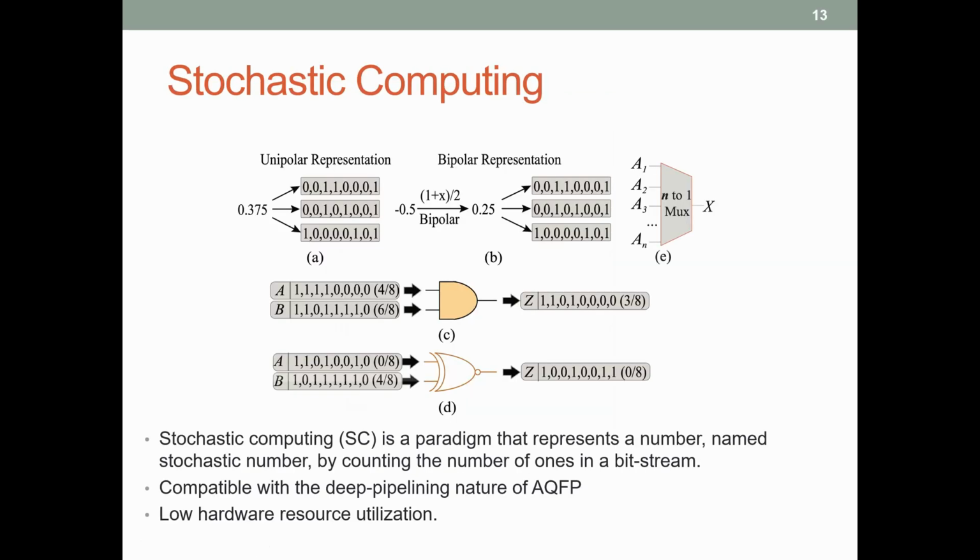So we have the synthesis and physical design framework. It means that as long as we have a circuit design, we can transform it through synthesis to the netlist, and then we can generate the GDS2 files, and then that's ready for the actual tapeouts and testing. Then we're using one example of deep learning acceleration to discuss our circuit designs and what will be suitable circuit design examples for the AQFP superconductor.